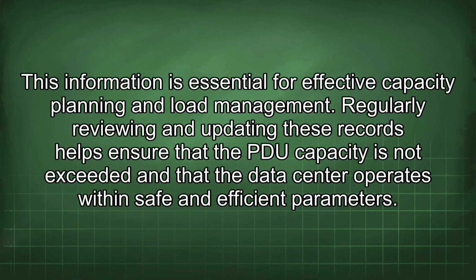This information is essential for effective capacity planning and load management. Regularly reviewing and updating these records helps ensure that the PDU capacity is not exceeded and that the data center operates within safe and efficient parameters.